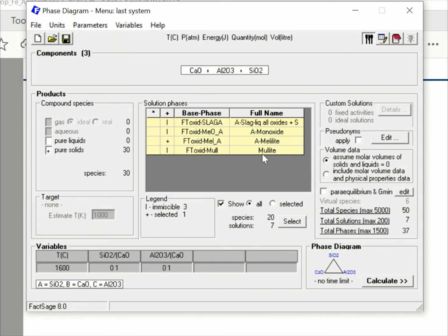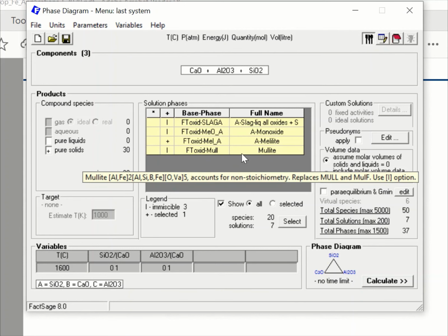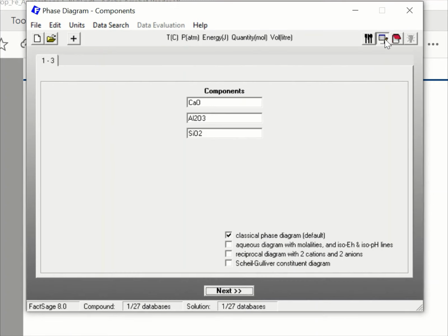Okay. So this is the ternary phase diagram. And then there's also some other thing you can do. You can make a quaternary phase diagram now. So for the quaternary system, let's just add one more plus and say MgO. I want to set the MgO amount as, for example, 10%, and then draw this CaO, Al2O3, SiO2 triangle diagram. Okay, you can see this kind of thing very often. Yeah, and I'm still using the mole, but you can use the gram, then you can have the weight percent.